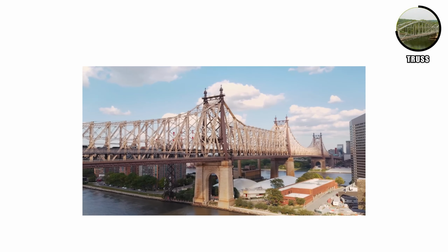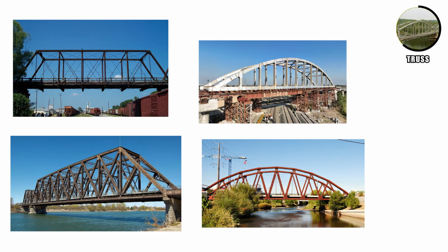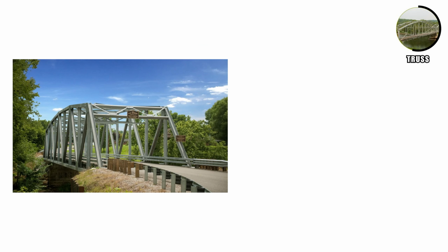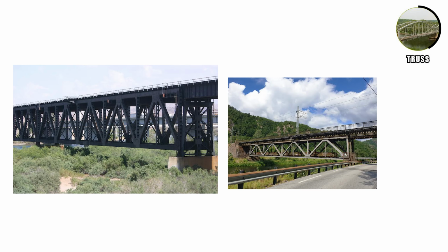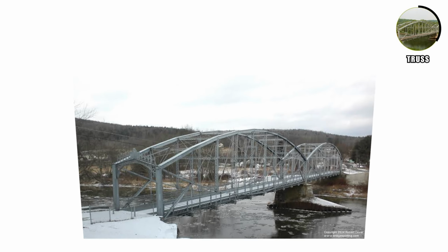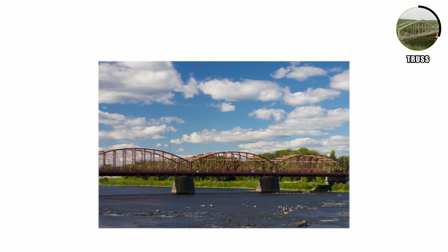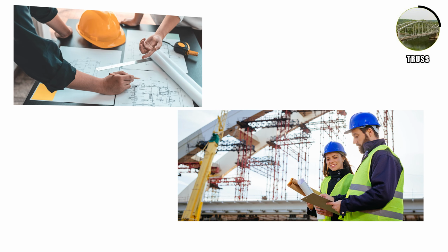distances than solid beams. Different arrangements have specific names: Pratt, Howe, Warren, bowstring, each suited to different span lengths and loads. A through truss puts the deck on the bottom level, so you drive through the framework, while a deck truss hides structural members below the road. Lenticular truss bridges are particularly photogenic, named because they resemble lenses, which are themselves named because they resemble lentils, which is the kind of naming logic engineers find satisfying.